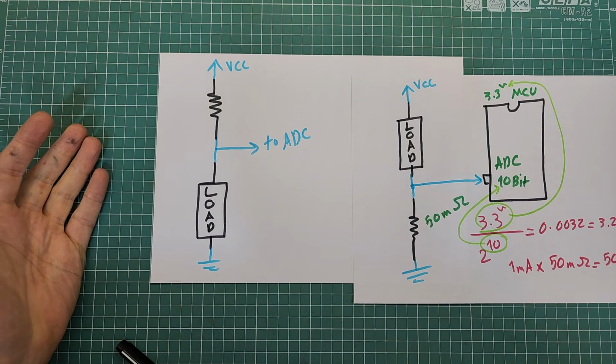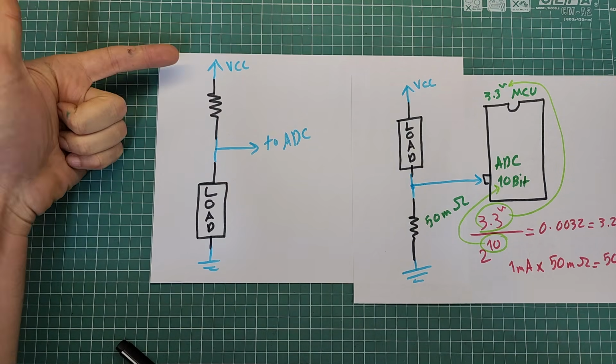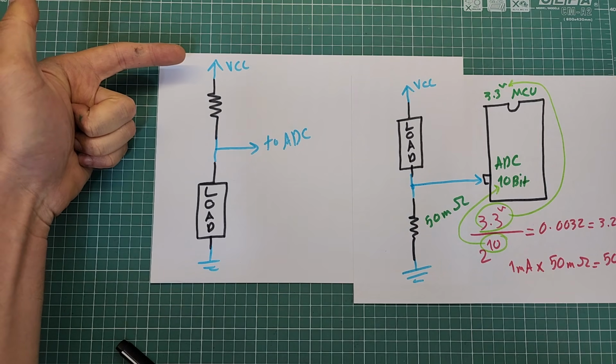You may ask why we have to measure the source voltage when we know what the source voltage is. Good question. Actually, we don't know what exactly the source voltage is. Most power supplies face voltage drop when the load draws current, which reduces the source voltage. Another example is battery-powered devices. The source voltage can be high or low due to the battery charge level. So, the source voltage is not known. What can we do in such cases?